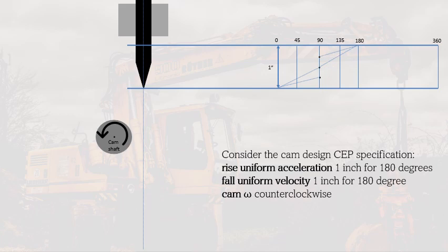And to locate the points, we are going to find the intersection of the divisions with these lines. So for 45, the intersection of 45 with the first line here that represents also the 45 is this point. For 90 degrees, it is this point in the center. For 135, this is represented by this third dotted line, and the intersection is that point. And we will also have intersection for 180 as well as for 0, as you can see there.